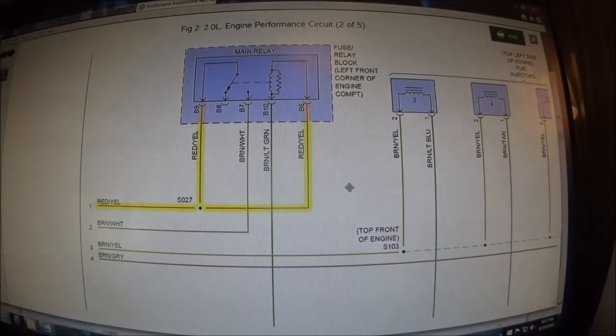Okay, so we made the repair, and I was pretty happy to find that. I figured, this is great news. Everything's going to be well again with this vehicle once I fix this wire. I repaired it. I went back to my scan tool and retrieved codes again. I went through the auto scan feature on the Autel, and lo and behold, I have communication with the PCM, and I have no codes in any of the modules. This was great news. So I tried to start the vehicle. Well, that's where things went bad again. The truck still wouldn't crank.